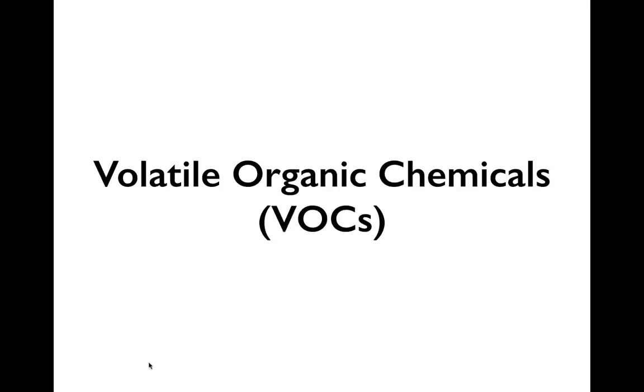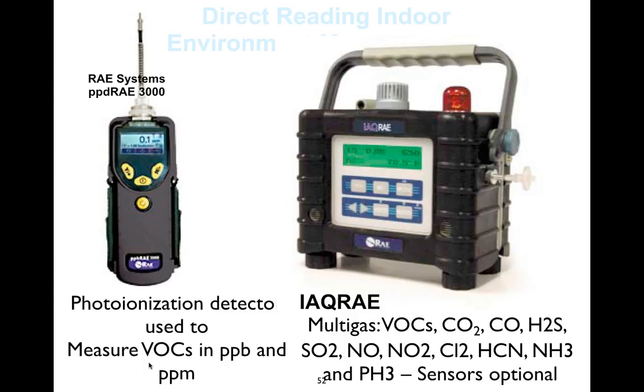Based on how quickly it declines, or dilutes with outside air, you can predict what the ventilation rate is that way as well. Next thing a lot of people are interested in is organic chemicals. You use solvents, cleaning chemicals, perfumes, food odors, you name it. There are all sorts of organic materials, new furnishings, carpeting, glues, magic markers, all contributing organic chemicals to the air.